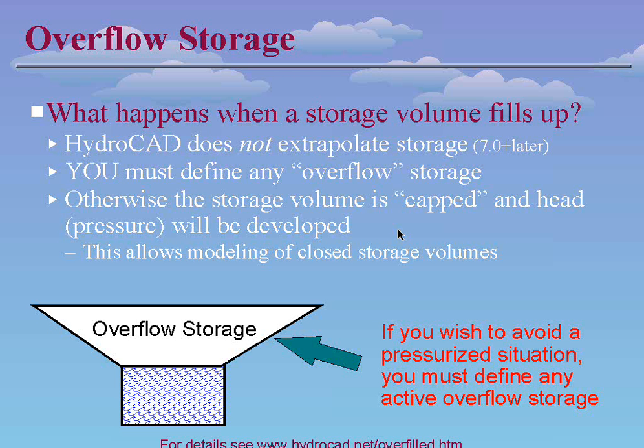If you don't do that, then the storage stops at the point that you tell it to. So if you only go to the spillway, you don't have any storage above the spillway. And then when the water is 1 inch over the spillway and the spillway is actually operating, the software doesn't know how much storage is in that 1 inch. That 1 inch might have 10 cubic feet or it might be 10 acre feet. So it's very important to know what the storage is.